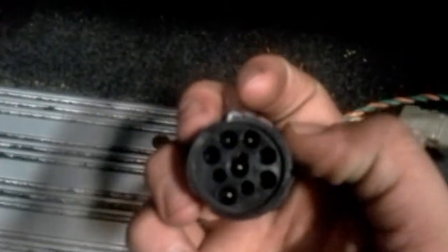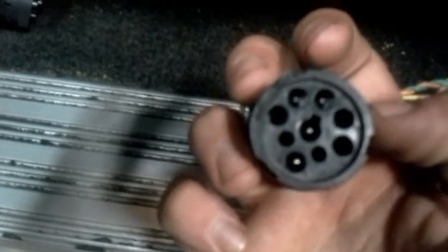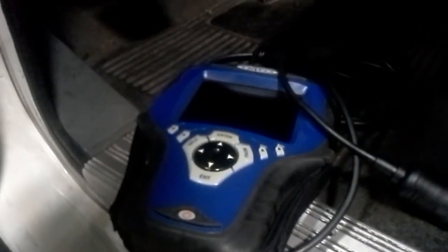Alright, so with that, guys, that's just how to look up codes with a handheld tester. Once you get done, you power down the code reader, unplug it, make sure it's unplugged all the way, and make sure you didn't damage any pin connectors inside here, or else the next person that goes to plug this in will get a connection error. Also, turn the key off, turn the truck off, make sure everything is all good so the batteries don't die. Alright, so with that, guys, that's how to run DTC codes on a handheld Genesis tester.